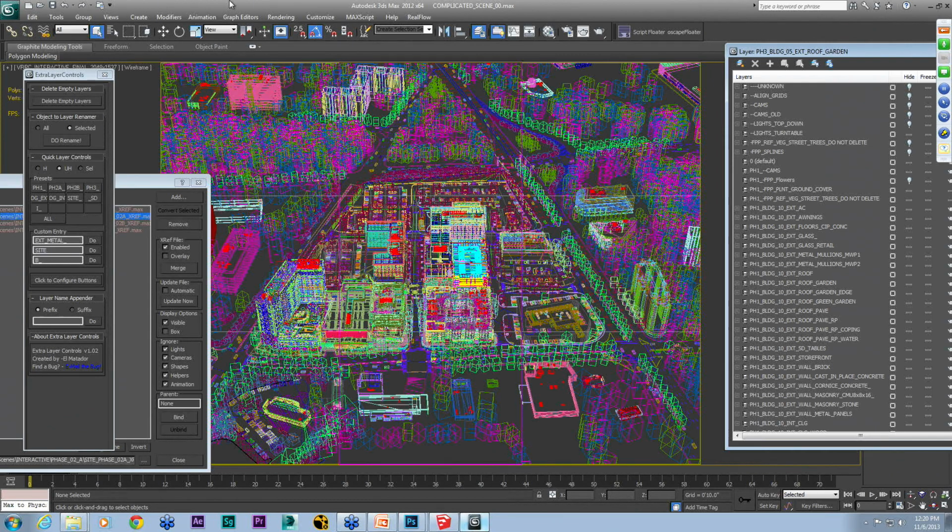Just one sec. To elaborate on that, we just imported a model with very complex geometries from Rhino, and there were lots of flipped normals all over the place. One thing you can do is in Rhino, weld all the vertices. Then when you bring it in, all the normals are going to be pointing at least in the same direction and not all over the place.